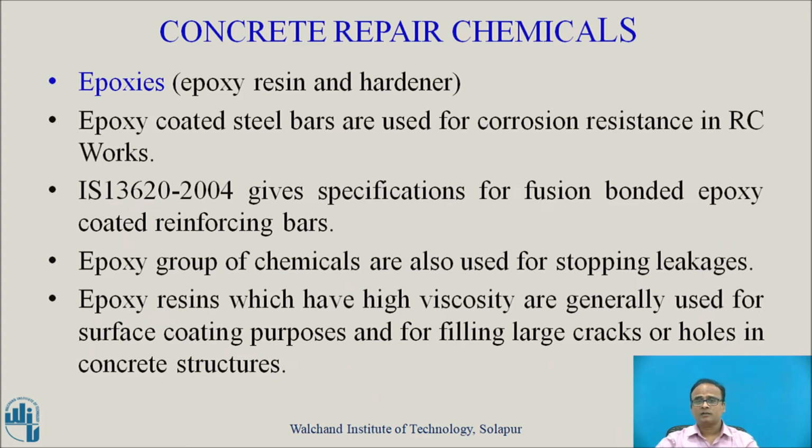Epoxies are coated to steel bars to protect against corrosion in RCC works according to IS 13620-2004, which gives the specifications or guidelines for fusion bonded epoxy coated reinforcing bars. Epoxy group of chemicals are also used for stopping leakages. Epoxy resins have high viscosity and are generally used for surface coating purposes and for filling large cracks or holes